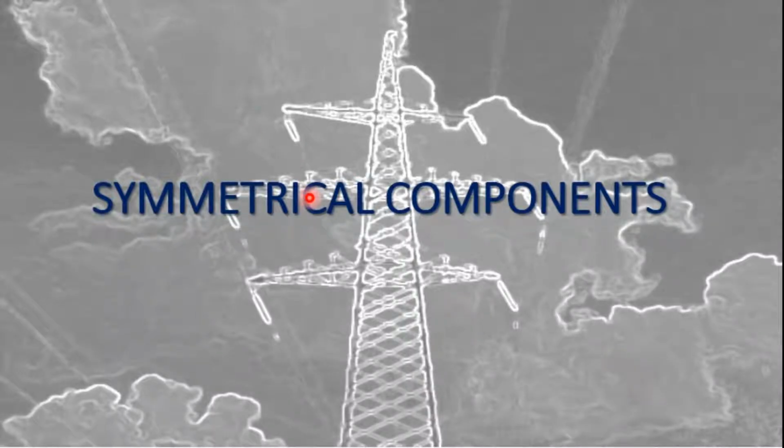Welcome you all to the next module, that is symmetrical components. We understood that a symmetrical three-phase system can be analyzed on a single-phase basis using the single line diagram and the reactance diagram. But an unbalanced three-phase system does not permit this simplification because it involves phases of different magnitudes and phase angles in each phase.